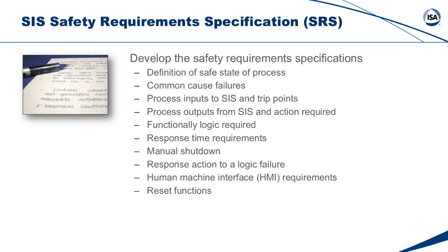If the system shuts down, you have a burner management system and you get high pressure and you get a flame out, and when pressure in the system shuts down, valves close. When pressure comes back to normal, do you want the valves automatically reopening? No. So how will resets be done? Because it's unique for each application and process, and the integrator has no idea what you need. So this needs to be specified in detail.